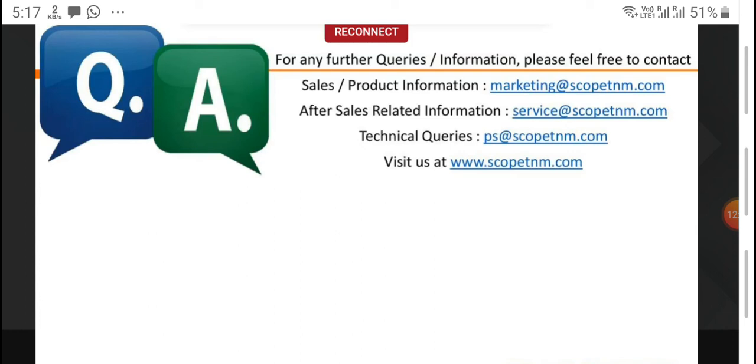Okay, so Murthy sir, I believe the first part of your question has been covered, that the system is an online system. So whatever is happening in the online state, that is in real-time condition, you are getting the fault location in real time only. Now, whenever there is a fault, let's say a fault occurred, the traveling wave will emanate from the fault point to both ends of the transmission line. After reaching the substation, let's say I talk about substation A only, one end of the line, it will be sensed by my system.